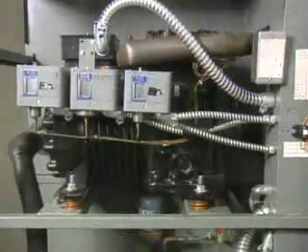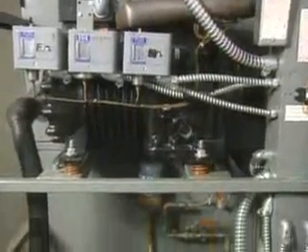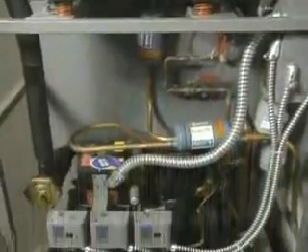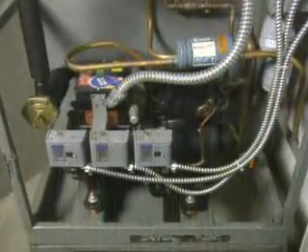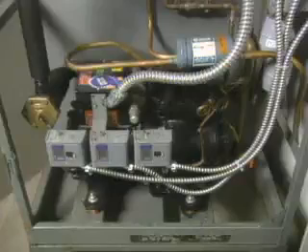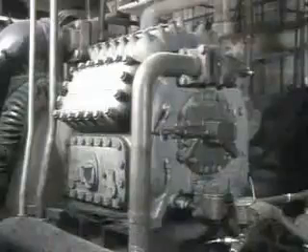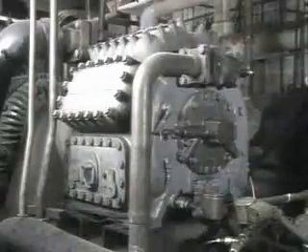Another indication of too little refrigerant may be a continuously operating compressor. Some types of refrigeration systems cycle the compressor on and off to maintain the proper cooling. If this type of system has too little refrigerant, the compressor may run continuously, trying to maintain the desired amount of cooling. A similar problem is low refrigerant flow. One place where this is a problem is in the evaporator. When refrigerant flow through the evaporator is too low, less heat will be removed from the substance being cooled. This will cause the temperature of the substance being cooled to increase. The compressor may also provide an indication of a low flow problem.